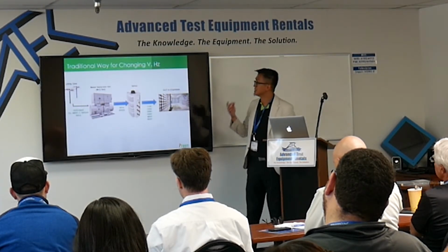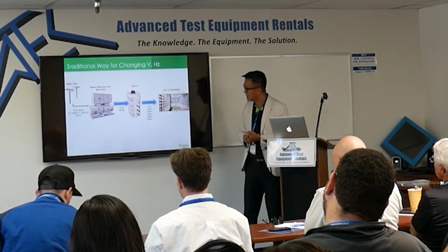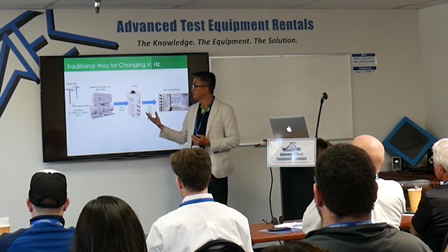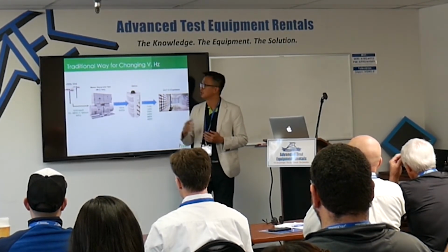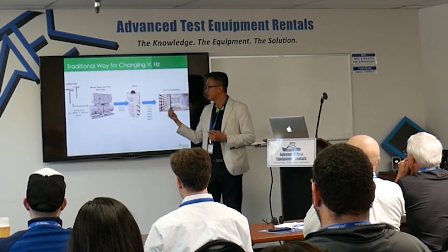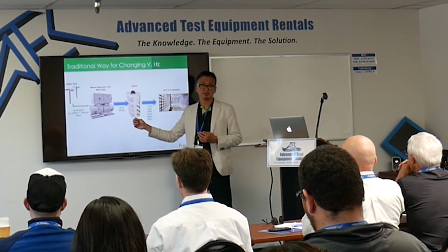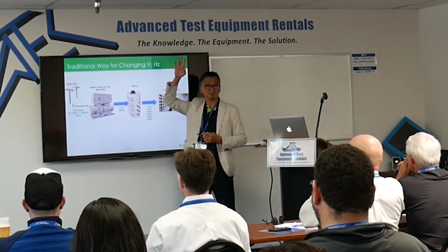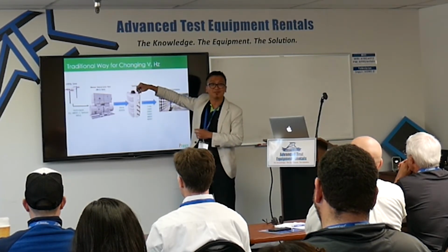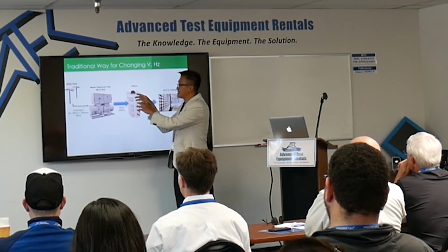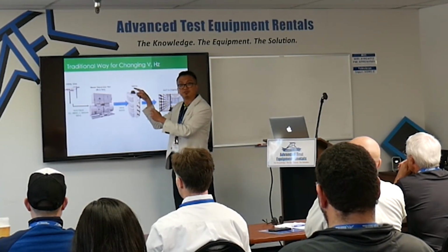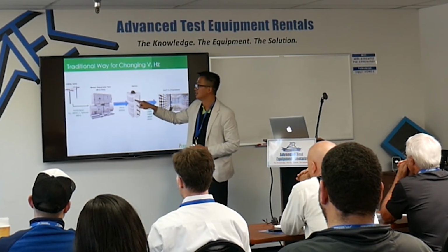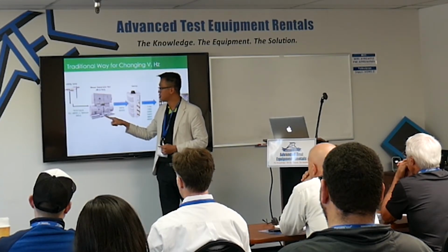So here are the applications. Most of the time you will see the typical, traditional way. If you want to test your unit, you will use a variac, right? To change like 110, 120, 208. Everyone sees this, right? But you have to turn the voltage. The other one is motor type. You have to push it up and down, and it may take a couple of seconds, like 30 seconds, to change the voltage. And you need to change your frequency.